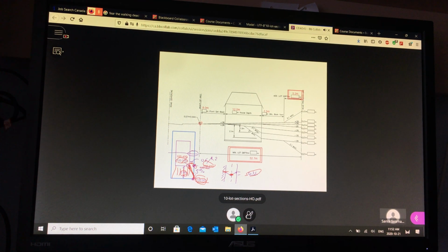minimum backyard. So instead of starting at 2%, I'm trying to go as high as possible at the back. So instead of using 2%, I'm going to use 3%. Right? So I'm going to use this one, not this one. So I want to start off a little bit steeper so that I can start to come up faster. Okay? So I'm going to use 3%. If I want to maximize how high I can be at the back, I'm going to use 3%.